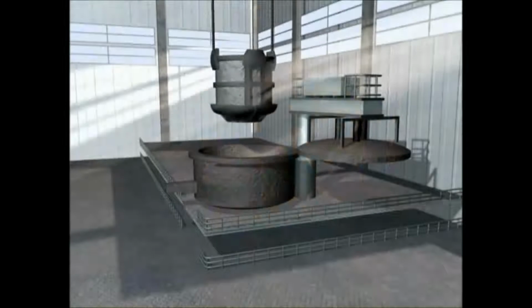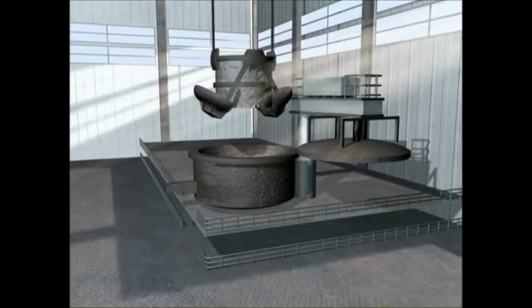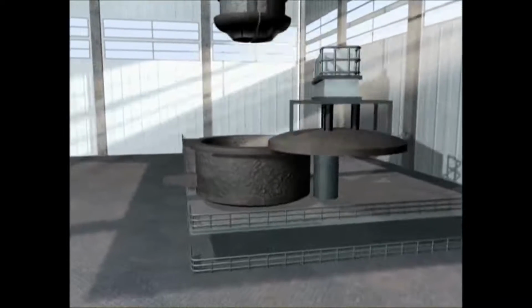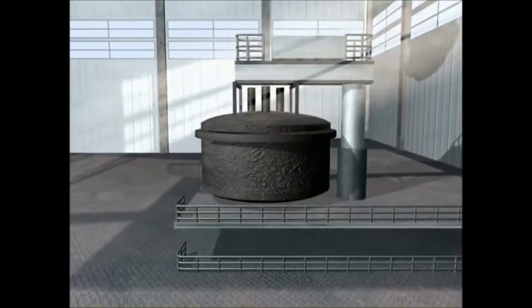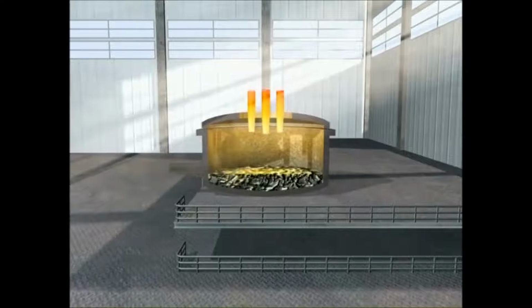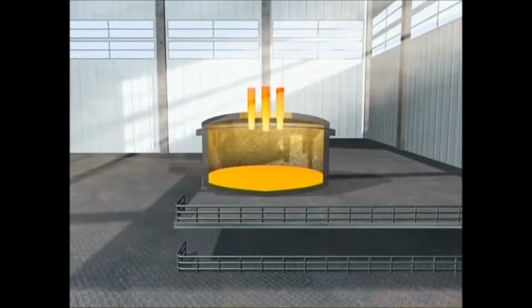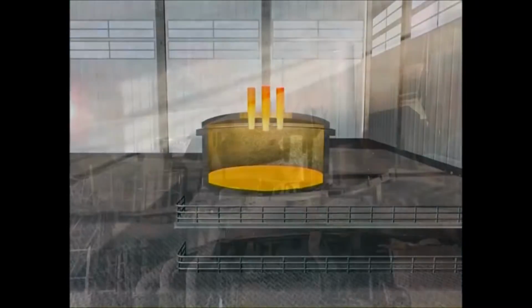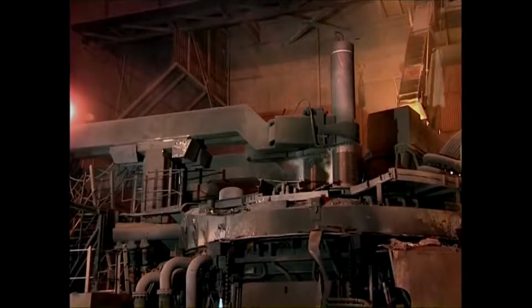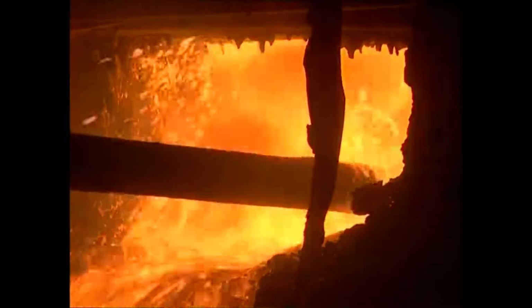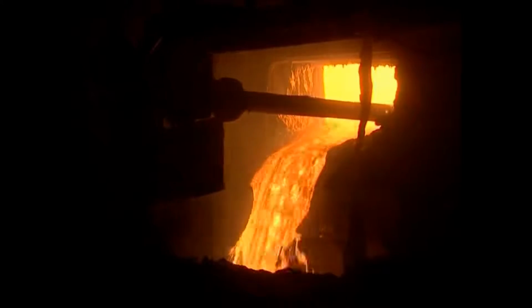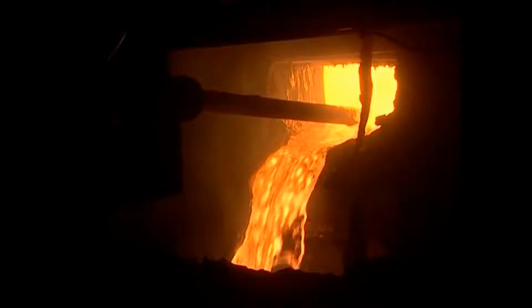The furnace is filled with recycled steel scrap. The roof is then swung into place and 3 graphite electrodes are lowered into the furnace. A powerful electric current is passed through the furnace. An arc is created and the heat generated melts the steel scrap. Lime and fluorspar are added and usually carbon and oxygen are blown into the melt. As a result, impurities in the metal combine to form a slag.